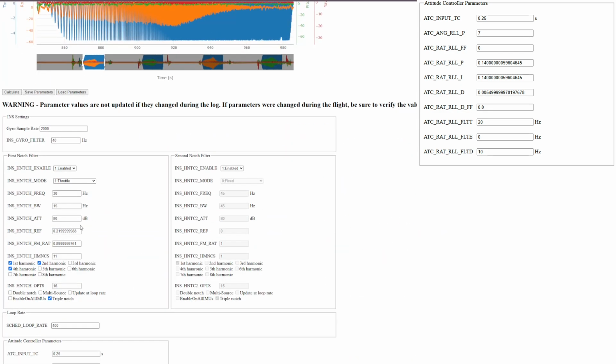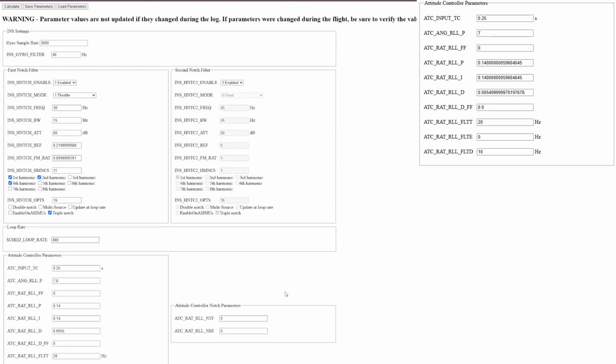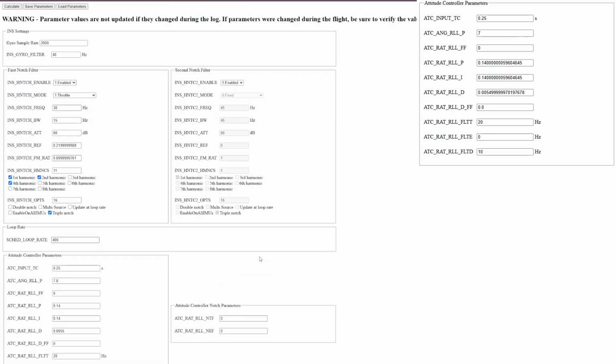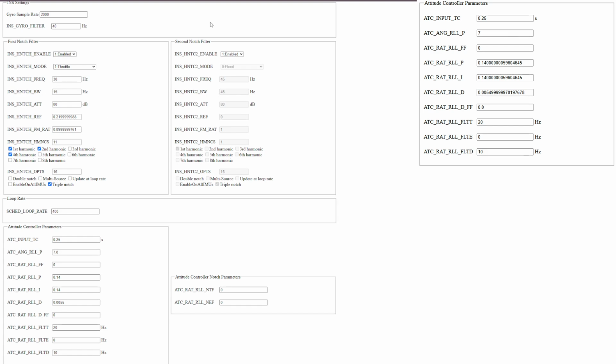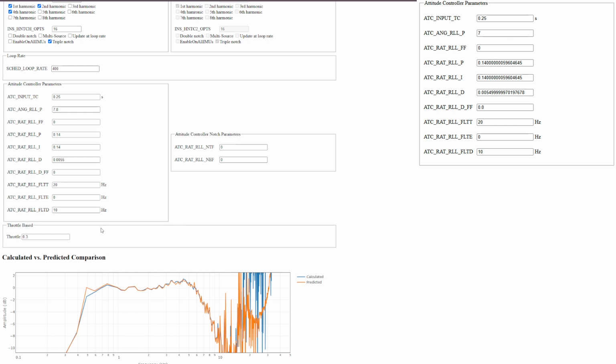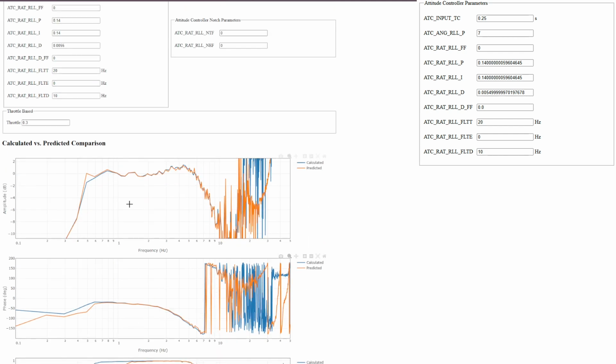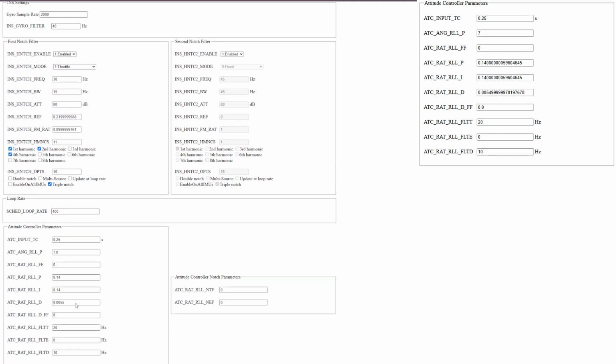Helicopters again rely heavily on the feed forward, so that requires some other steps as well. And of course, all of these filter settings also impact this tune, and you can look, for example, at how reducing the D filter settings actually allows you to push the D term up further by making the control loops faster. What this doesn't show, though, is the impact of noise through the system.